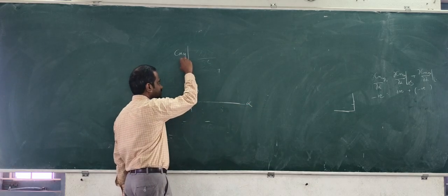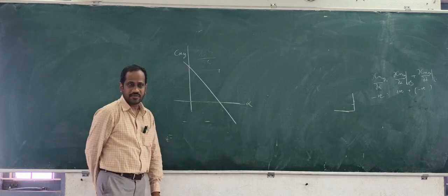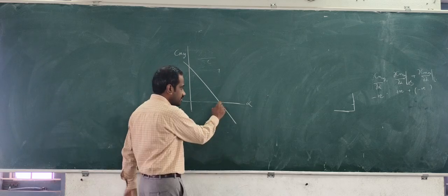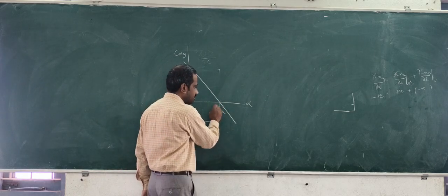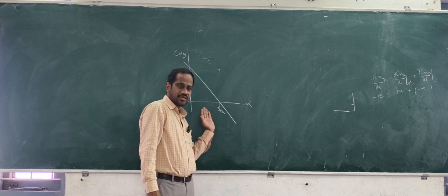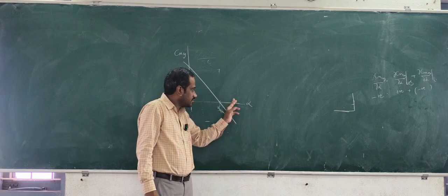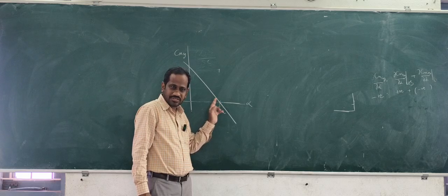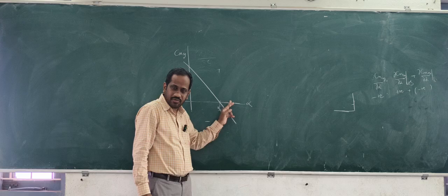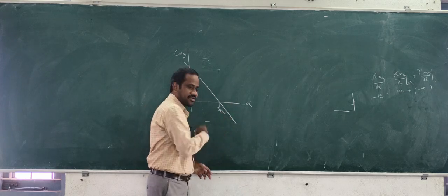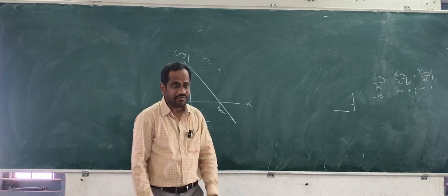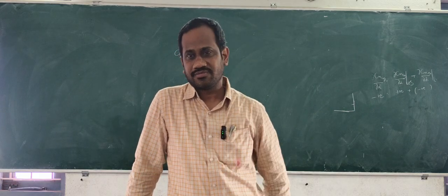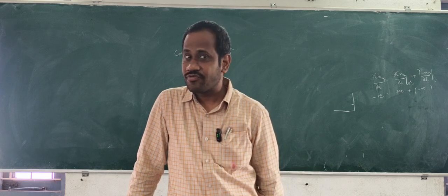So we had discussions. This is how the aircraft behaves. These are all the restoring pitching moments if the aircraft is disturbed from its trim or equilibrium angle of attack. If the aircraft gets into an increased angle of attack due to disturbance, the aircraft should try to return towards the equilibrium angle of attack. How is that possible? Only by creating this type of restoring moment. So the type of restoring moment the aircraft has to generate if disturbed from equilibrium angle of attack is the criteria. It's the behavior of the aircraft during disturbance.